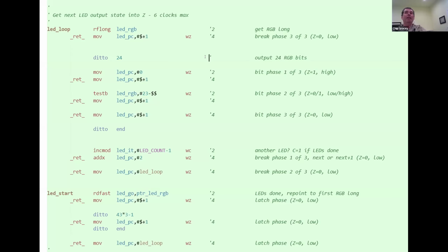Well, and I really had to do that because of the way I designed the hardware. On the falling edge of the clock, you're always updating whatever the LED bit stream state is. So those things were married. I couldn't put them on separate cogs because the cog that's raising the clock to run the serial chain is also the cog that's dropping the clock, which is then responsible for the LED states. Does that make sense?